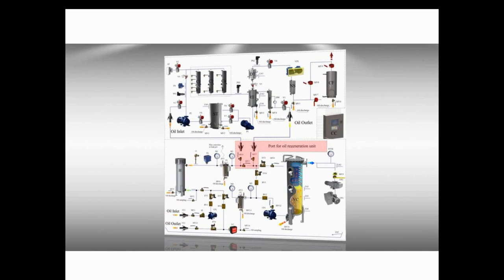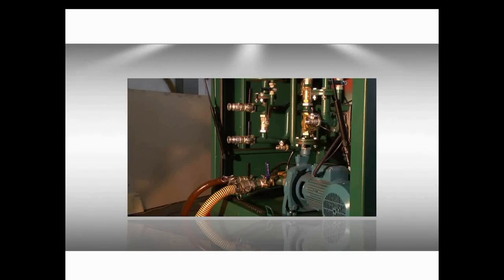Do you remember that during this talk we have been touching on the advantages of regeneration versus oil change? Now we've got them. No interruption of transformer operation, which could bring a customer to money loss. No environmental spoilage. No exposing of the transformer core to the atmosphere. No regasketing of the top cover. Independence of ambient climatic conditions. Low labor cost, which is a result of one operator serving the plant. Complete flushing of the transformer and its core, which is most important.